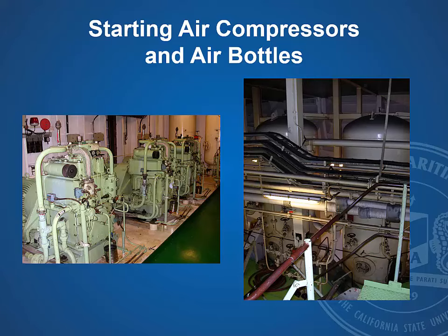You'll either have also a smaller, what they call a topping up air compressor, or with the one with the simulator, the emergency air compressor. These are smaller units. With a topping up air compressor, that one would be used out at sea, and instead of a main air compressor coming on to bring the bottle up, these little topping air compressors are there just to keep the bottles full when there's a light load.